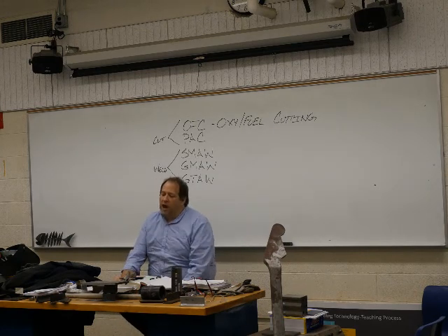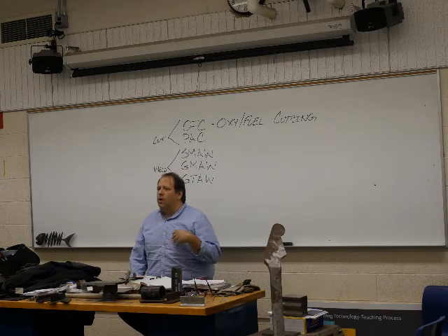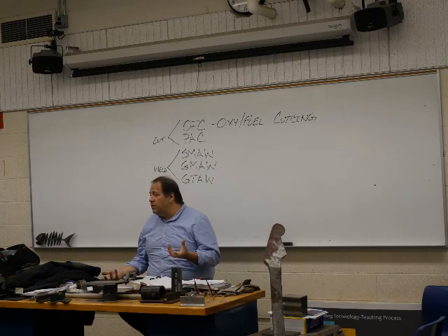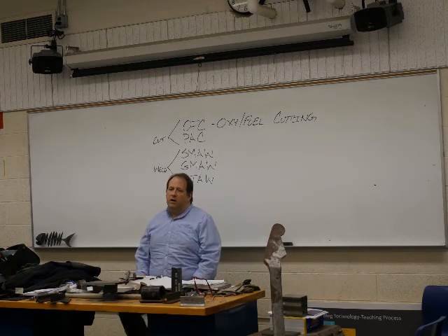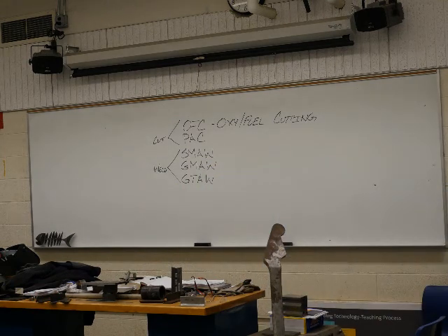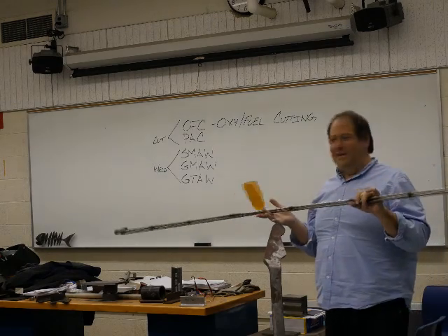So we don't actually cut by melting it, we cut with an oxidizing process. You get really good with the torch, then you can expand, you get better and better. Graduate to something like this. This is a torch. This is not a precision cutting tool at this point.